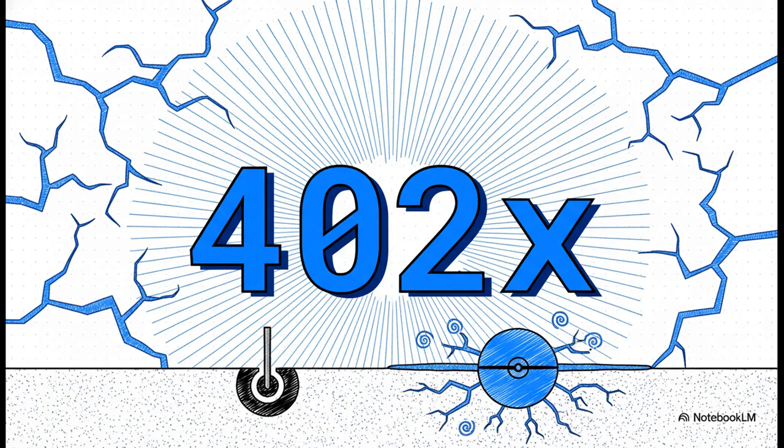Now, when you plug a -6 into the well deliverability equations, it multiplies the effective wellbore radius by an astounding 402 times. You haven't actually made the physical steel pipe in the ground any bigger, but mathematically, as far as the reservoir is concerned, the drain just got 402 times wider. That is how you unlock massive production from otherwise stubborn, tight rock.